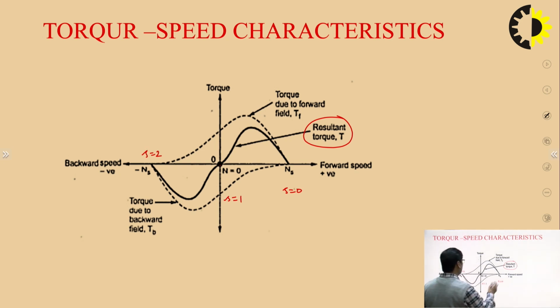So this is how it is varying. The initial torque on the rotor is 0, the rotor will not rotate, hence the single phase induction motor is not self-starting.